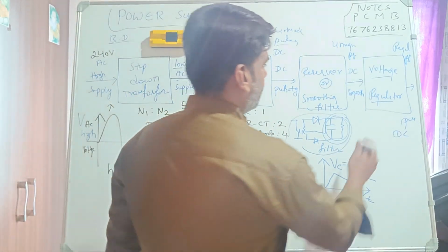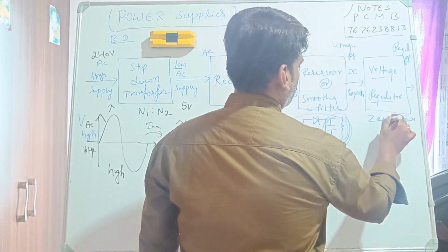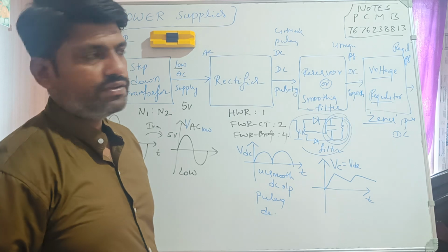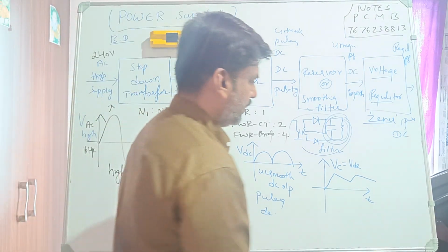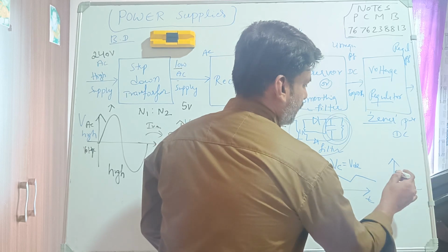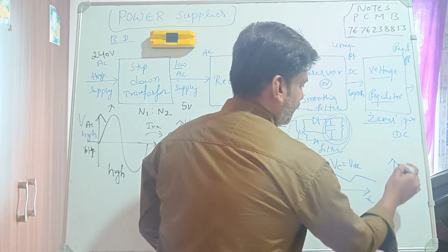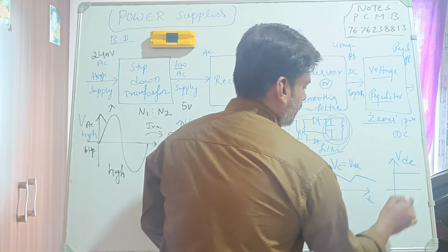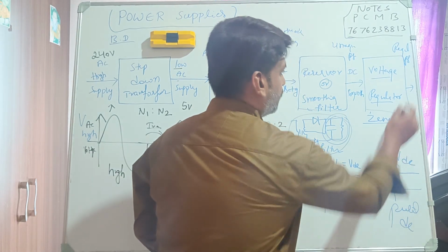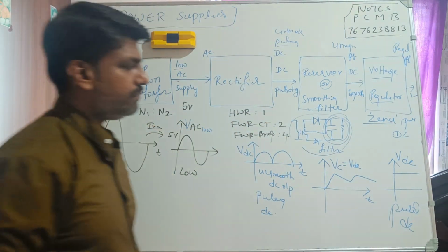What type of voltage regulators can we use? So Zener diode we can take as an example, which acts as a voltage regulator, so that we are going to get the constant voltage at the last. So this waveform is getting changed to this. So we'll call it the purest form of DC. That is what the output here we will get, right?